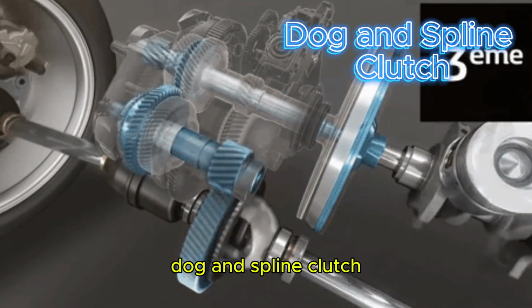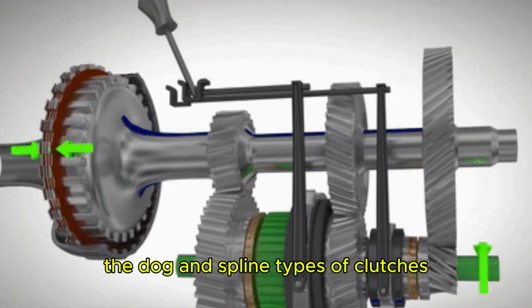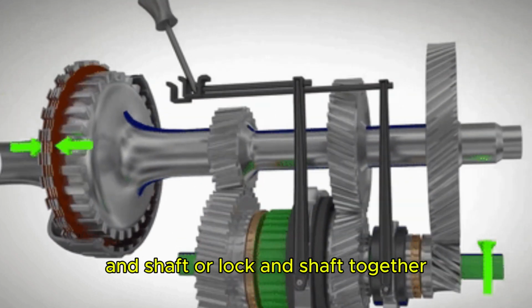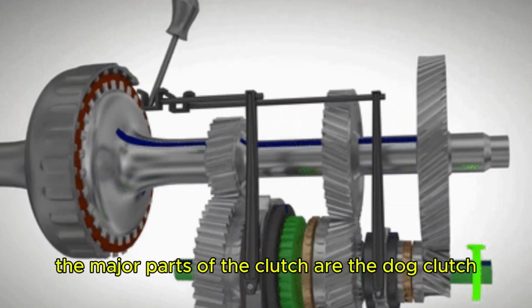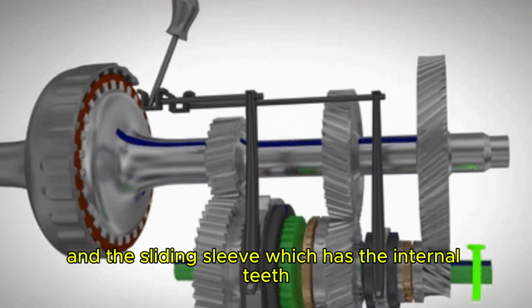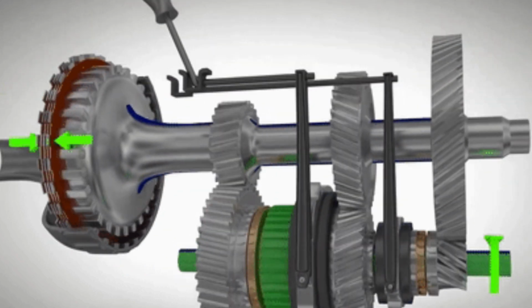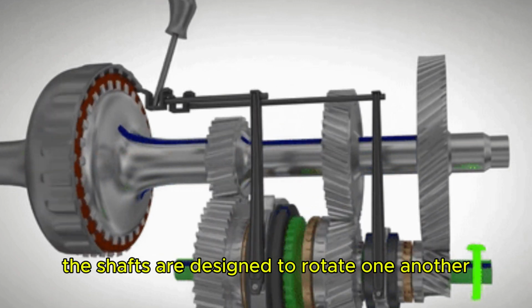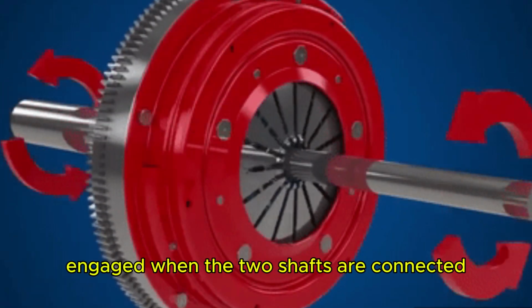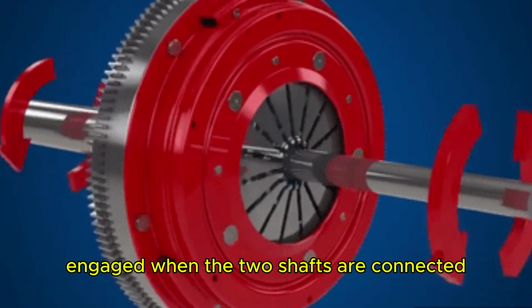Dog and spline clutch. The dog and spline types of clutches are used to connect the gear and shaft, or lock and shaft, together. The major parts of the clutch are the dog clutch, which contains the external teeth, and the sliding sleeve, which has the internal teeth. The shafts are designed to rotate with one another at the same speed and will never slip. The clutch is said to be engaged when the two shafts are connected.